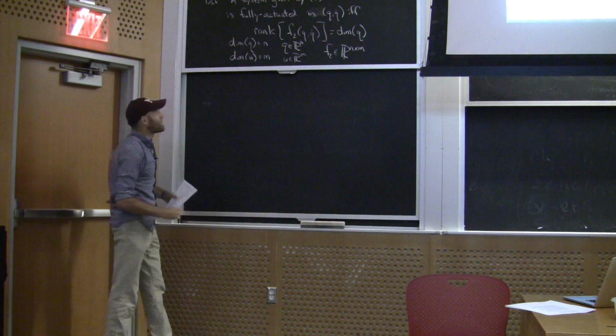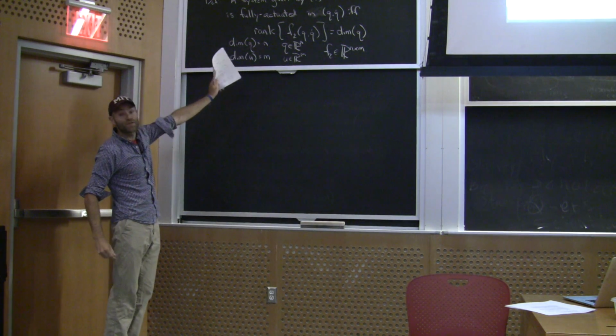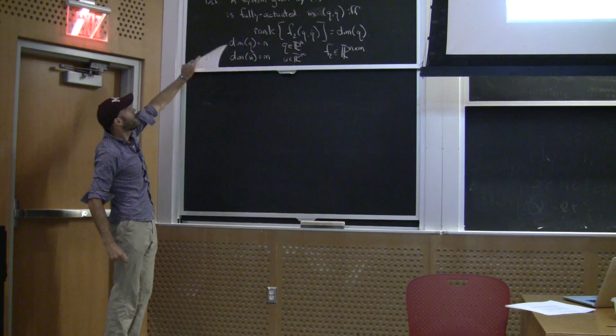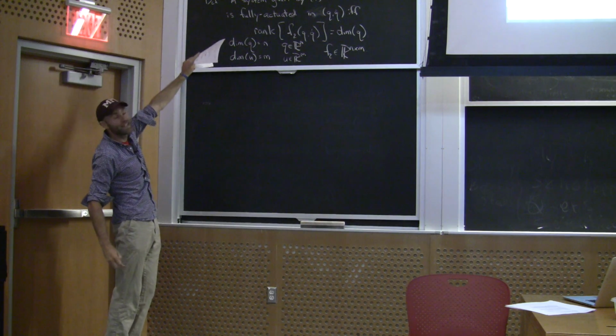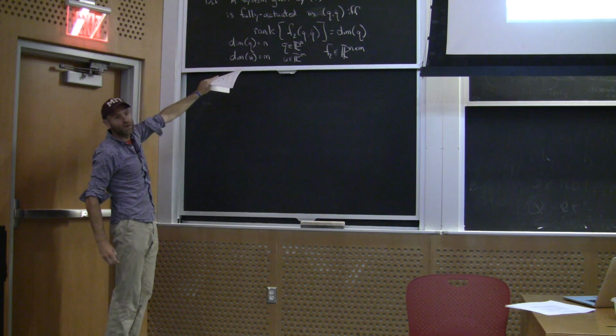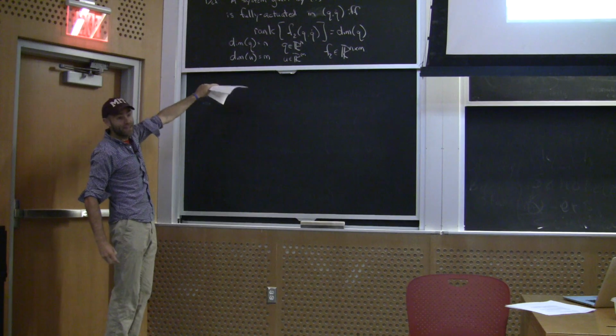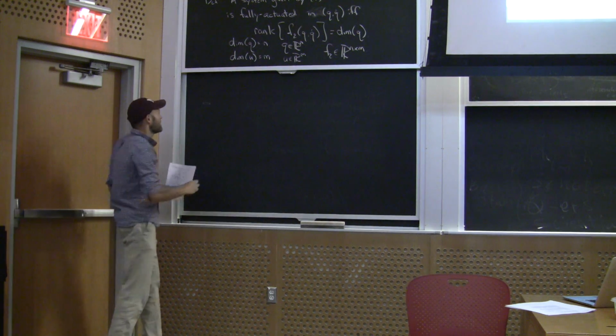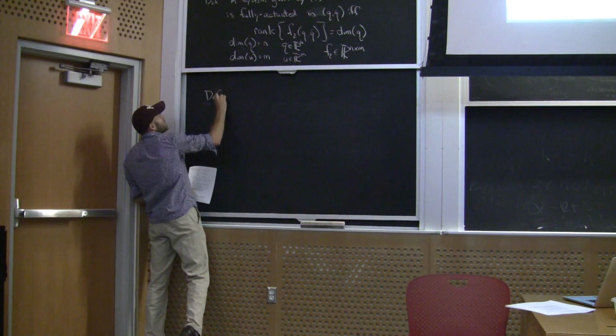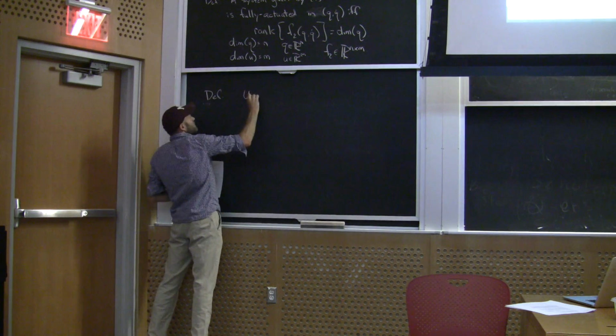Basically, if I can take an inverse of F2, then my claim is if your robot has dynamics of the form where you could take an inverse of F2, then your robot is simple to control. If you can't take an inverse of F2, it's really hard to control, or it's harder. That's what we're going to talk about here, right? So, of underactuated system.